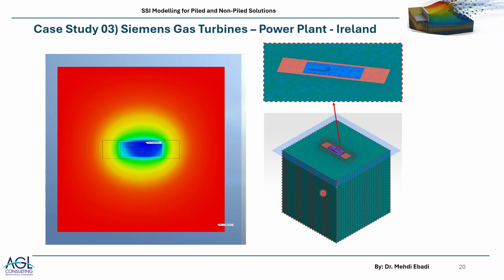Okay, what were we asked for? We had a Siemens specification, and in the Siemens specification, there were different items to be checked. One of them was the load deformation behavior under different load combinations, which were live loads as a category, accidental loads like blade loss and those kind of loads as another category.